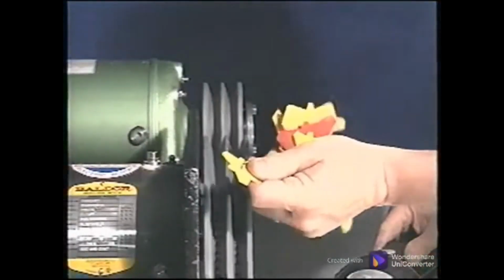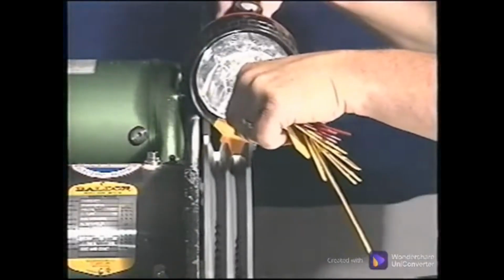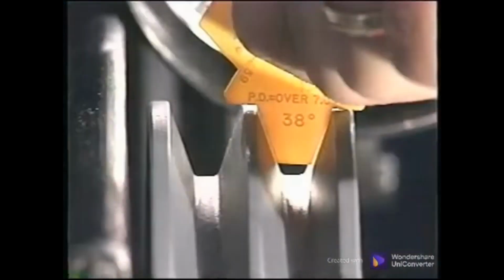Use a sheave groove gauge and a flashlight to check the grooves for dishing or abnormal wear. Misaligned sheaves may wear more on one side than the other. If any clearance is visible, the sheave should be replaced. A new belt placed in the sheave should be flush with or above the outer diameter of the sheave. If the belt is below the outer diameter of the sheave, it is worn too much.